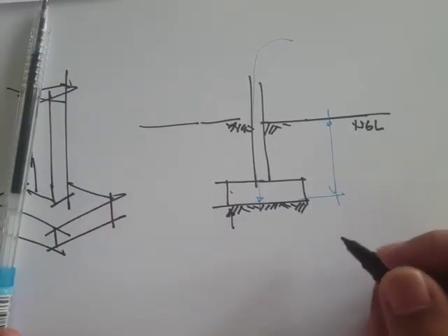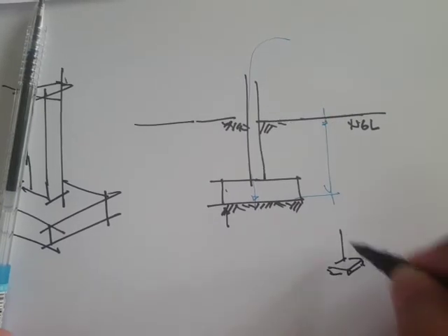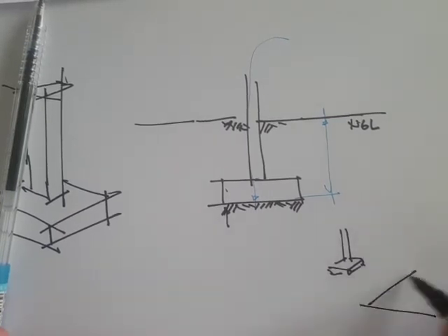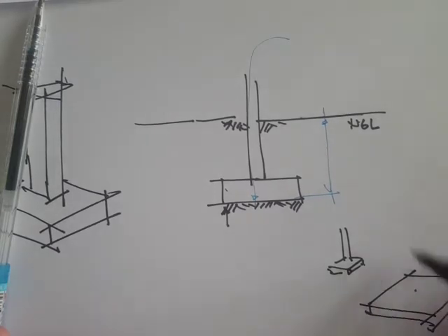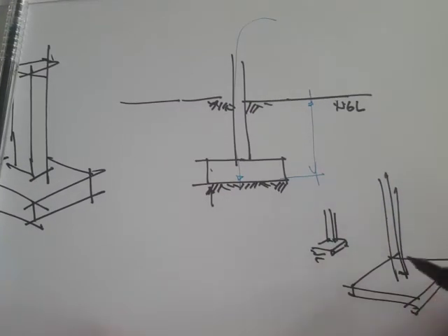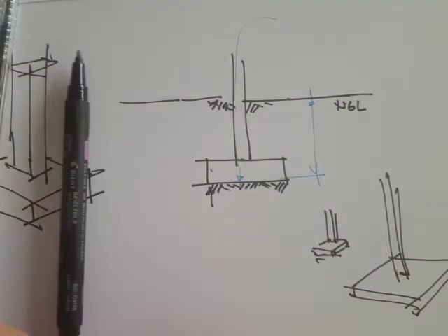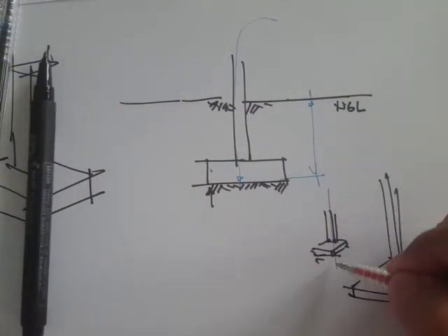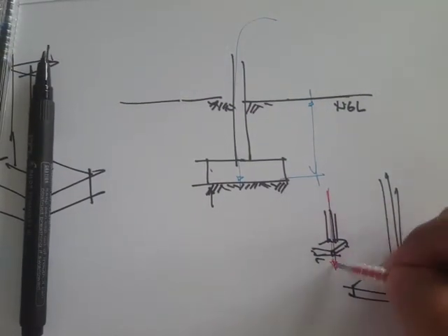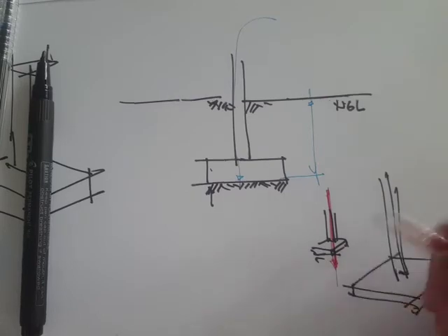Actually the principle is that if your footing is just like this, and then compared to a footing for the same loads like this, then let's assume the same loads and the same bearing capacity of the soil, then this can induce high pressure, so it can probably punch through the soil.